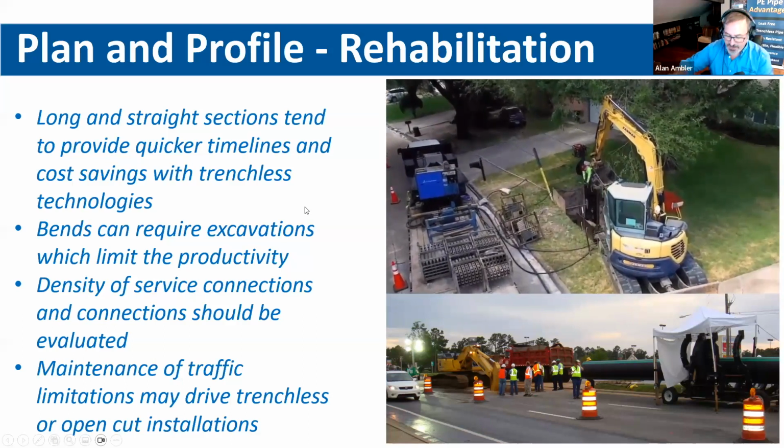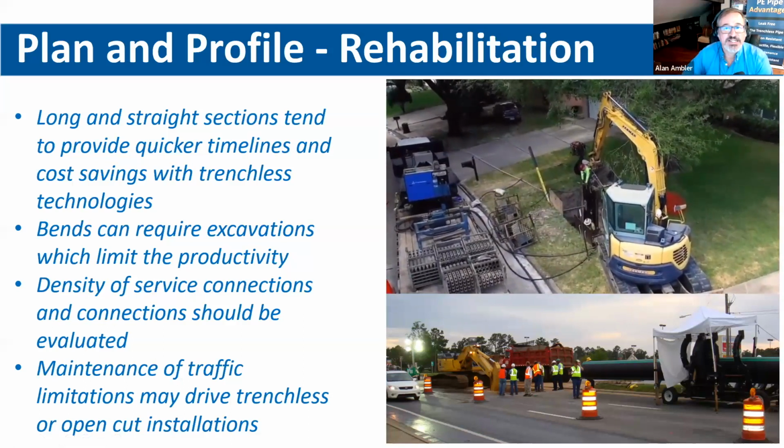Absolutely. So we've got a great question from John Jackson about pricing, in comparison between trench installation of PVC versus pipe bursting with HDPE. Oh boy. It depends really on your area, where you're at, what's going on with the install, who the contractor is, and all sorts of different things. Regionally, it makes a big difference if there are more contractors familiar with the trenchless installation itself. There's a whole lot of contractors familiar with open cut, so they've got a better baseline as far as costs are concerned.